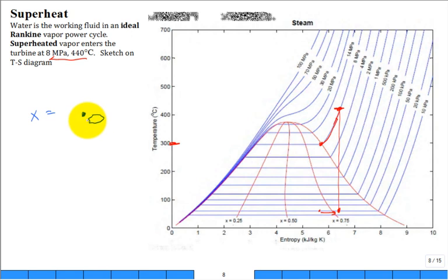Well, they're very dense. So if there's any bending, turning of the fluid, which there are next to vanes, when it's in your fluid mechanics, we do all this vane calculations, getting a pressure and a force on your vanes. So your fluid stream comes in and turns, and then you get this force in that direction and helps rotate the machinery. So anyway, the gas, vapor, oh sure, it bends and turns. What about the solid little chunk of high density water that's in it? It wants to still go on a straight line, and so it's going to possibly go and impinge on some of your blades.